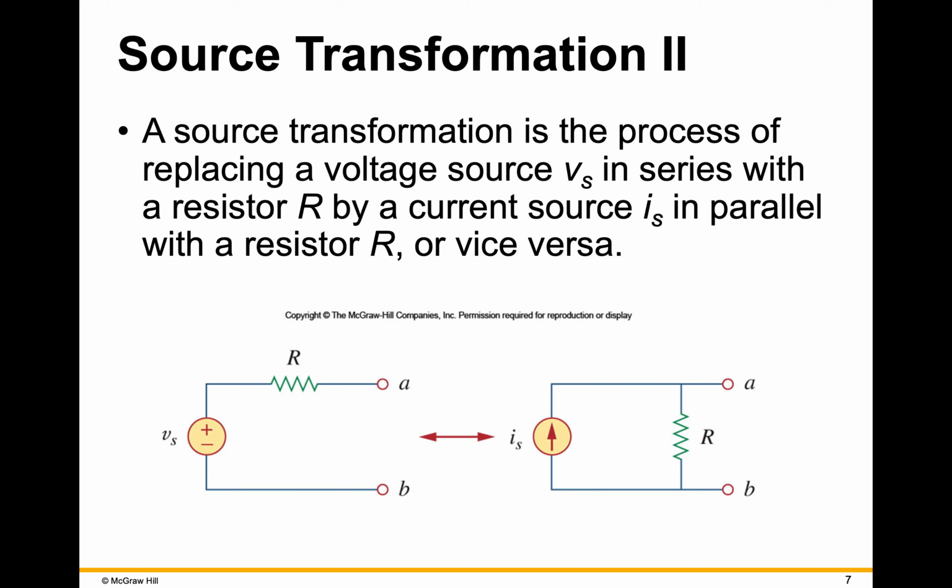So what we're really comparing is the voltage between A and B with the circuit on the left and the circuit on the right. If we short the terminals, the voltage from A to B will be zero, and so we're looking at what we refer to as the short circuit current. So I'm going to be using these expressions in the next section.